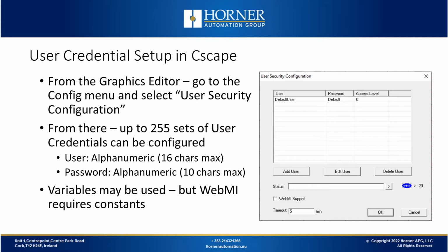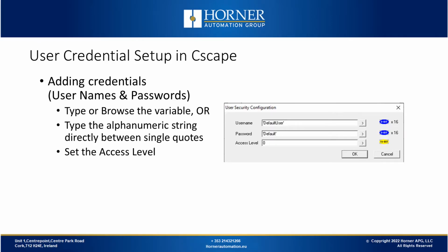Generally, I would recommend that you hard code in these user credentials. You could also assign variables to those credentials. WebMI requires constants to be entered in, however, and you don't have the ability to use variables for your user credentials. Keep in mind you can enter up to 255 sets of credentials. When you decide to add credentials or edit existing ones, it's just a matter of pressing the appropriate button for edit or add, etc. If you're using a variable for username or password, you just select browse and then select the relevant variable. I recommend hard coding the username and password in between the single quotes.